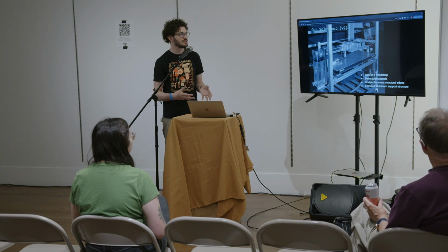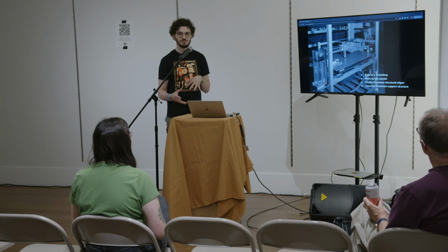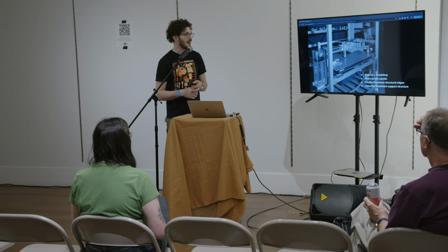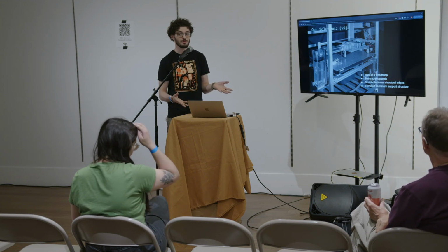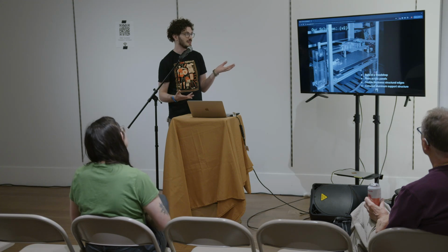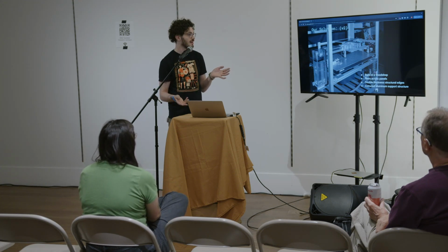And the big change with this was we actually moved away from digital fabrication to more traditional fabrication techniques. So the entire flume was built in a wood shop, not in our lab that has a laser cutter. And we used much thicker acrylic, which again, it's really easy to use thick acrylic with woodworking tools. It might be hard to cut like 1/2-inch acrylic with your 35-watt laser, but a table saw doesn't care.